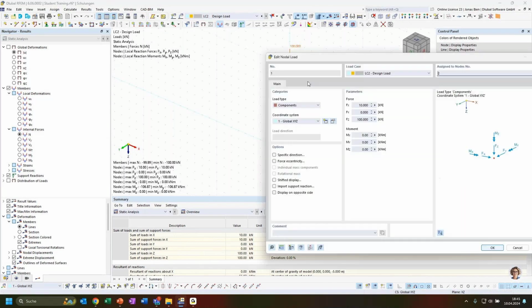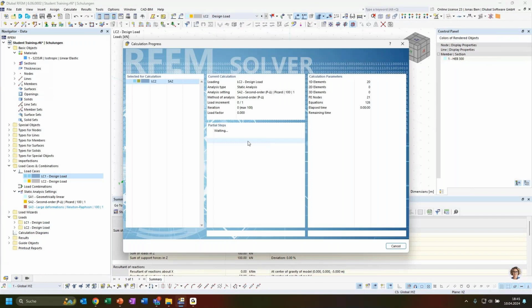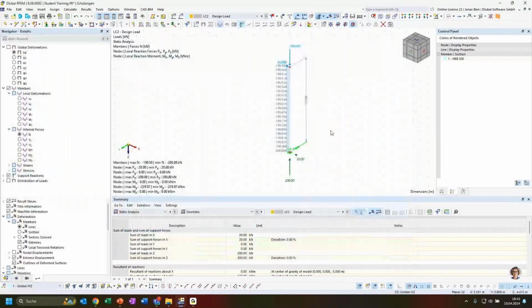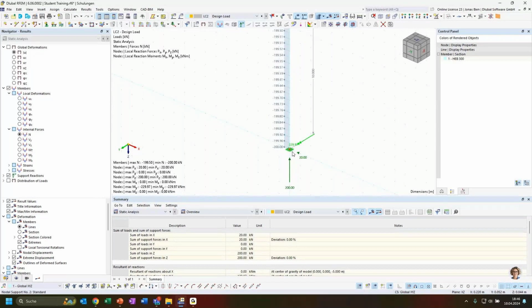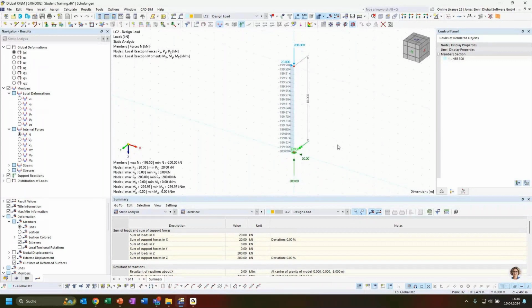So, for example, in the second load case, we can double the load. And I want to show you, let's compare the reaction we are getting now. As I said before, we had an increase of the resulting bending moment at the column base of 7%. But now if we compare the results, we have an increase of almost 15%. So we would expect 200 kilonewton meter from our horizontal load, but now we have 30 additional kilonewton meter just from the horizontal load times the deflection. So we no longer have a linear proportionality between the external loading and the reaction force. So that needs to be kept in mind.